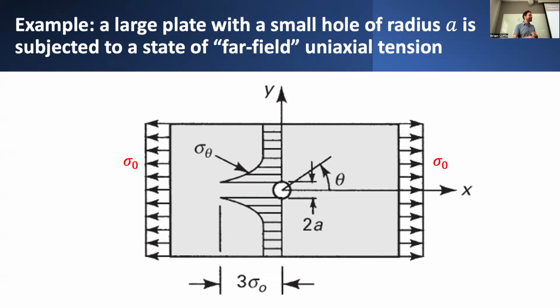And to really assess that, we need to know what is the distribution of stress that would happen if we introduce this local defect or local modification to the geometry in a member that would otherwise have seen basically just a constant state of uniaxial tension. So if the hole was not there, then the solution to this problem is very easy.